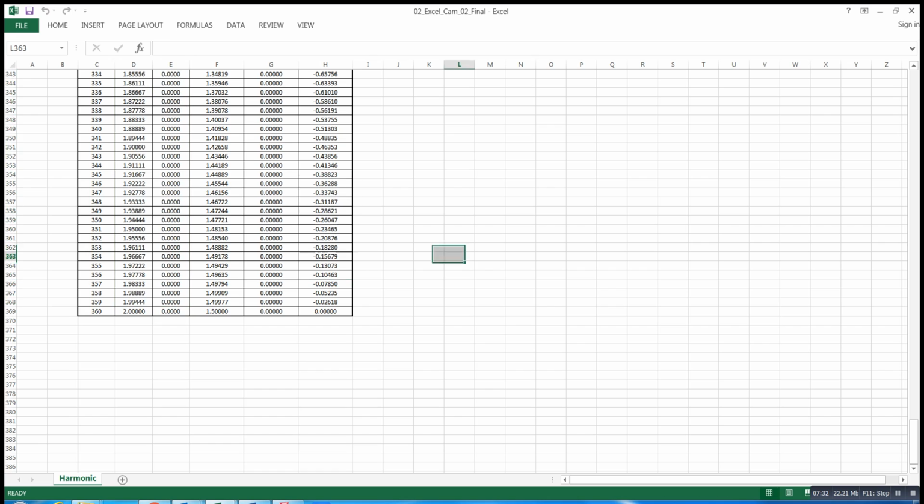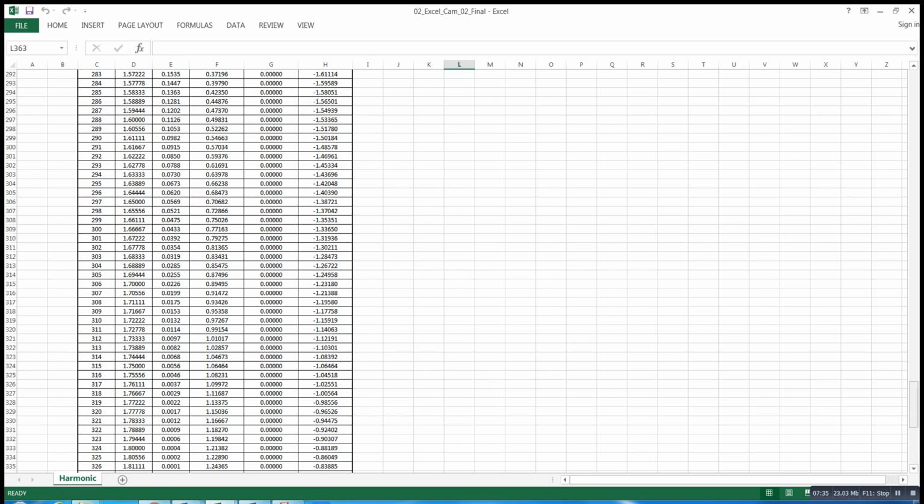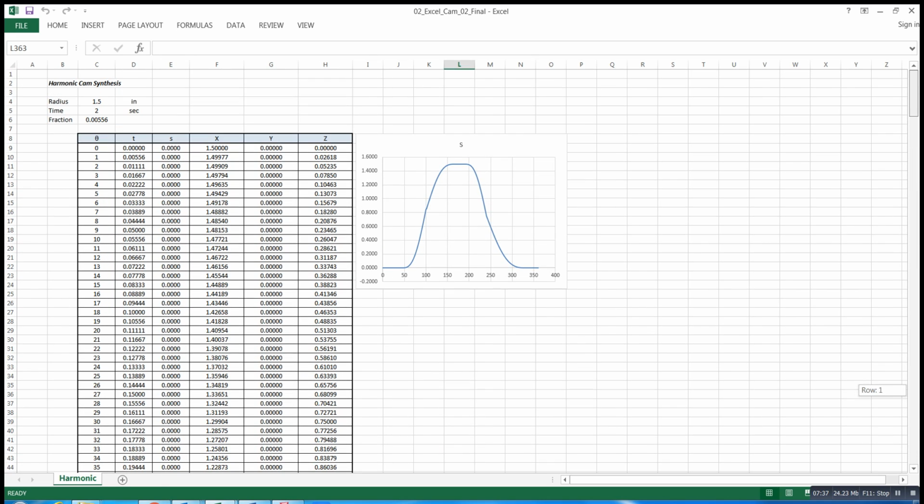Okay. The file with the values of the S versus time. Since we are having 0.5 revolutes per second as the velocity of the cam, every 2 seconds we have a full revolution, and we need the time that the cam spends on every degree.